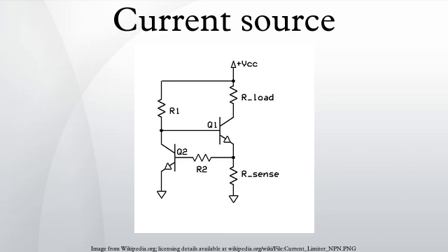Since Q2 is dissipating very little power compared to Q1, Q2 will not heat up any significant amount and the reference voltage across our sense resistor will remain rock steady at 0.6 V, or 1 diode drop above ground, regardless of the thermal changes in the VBE drop of Q1. The circuit is still sensitive to changes in the ambient temperature in which the device operates as the BE voltage drop in Q2 varies slightly with temperature.